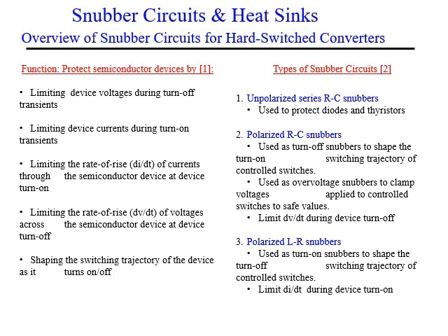Let's go to another point, which is the protection of these converters. From what do we protect them? We protect them from electrical phenomena and thermal phenomena. Let me start with electrical. For electrical, as you know, when it's switched on and switched off, the rate of change of current and voltage is high. Okay, at the beginning, changing from 0 to the full load voltage in a small time, in microseconds,